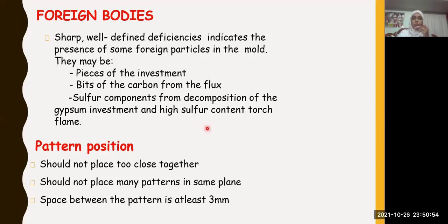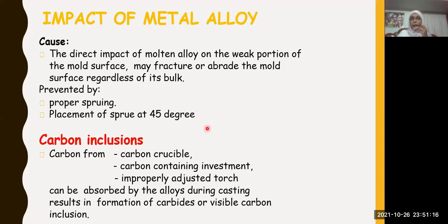Next is pattern position. How you place the wax pattern inside the investment ring, the casting ring, is also very important. You should see to it that you are not placing two wax patterns too close to each other, and you can't place all patterns in the same plane. You have to change the plane, and at least 3 mm of gap should be there between the adjacent patterns.